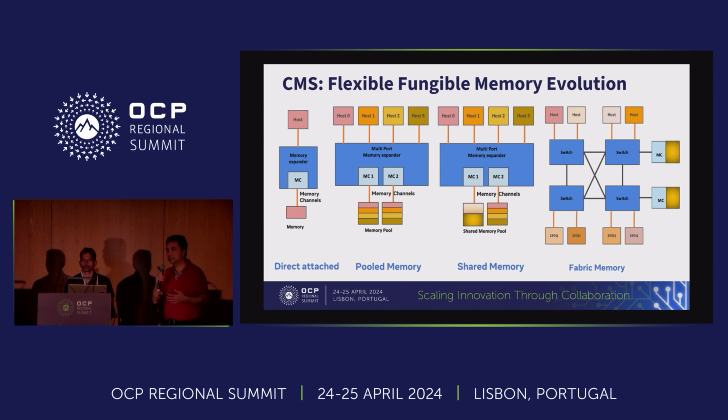So in other words, CXL is not just the physical layer, although it is relying on a well-known PCIe physical layer today, just so that people know how it is and work with it immediately. But it has multiple other layers that the community of software and hardware people are getting together to develop the entire system. So as an example, physical layer can be remapped into UCIe. CXL protocol runs on UCIe, but the rest of the ensemble of work that's being done can be transferred to others' physical layers as well.